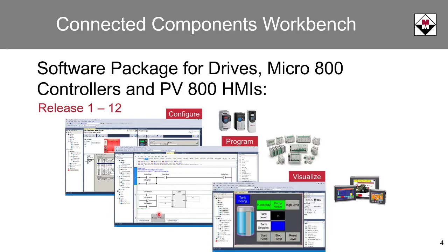We'll start with Connected Components Workbench, also known as CCW. This software package programs Rockwell's small standalone controllers, the Micro 800s. The Micro 800 part numbers start with a 2080. They are a great migration option for those old discontinued Pico controllers and MicroLogix controllers.